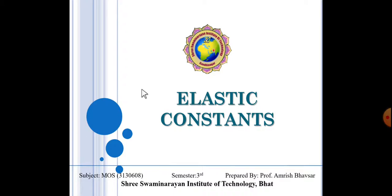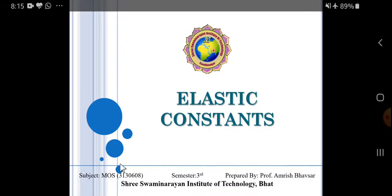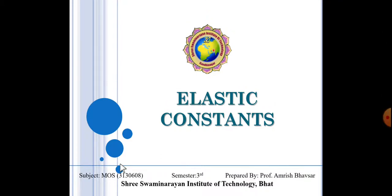That elongation delta L will be calculated by the equation L alpha T. In that, L is equal to the length of the member, alpha is equal to the thermal coefficient, and T is equal to the temperature. So, instead of P, here temperature plays the important role.